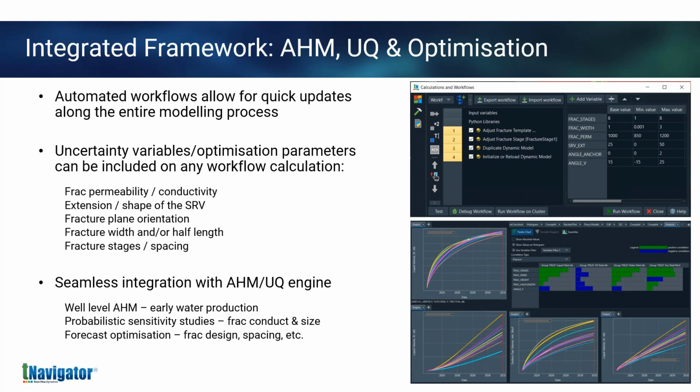Fracturing parameters among rock properties and pumping schedule can be set as variables to optimize the processes of fracking. The different modeling steps, either when using Fracture Simulator or when using any of the described hydraulic fracturing methods specified with direct inputs of the parameters, can be recorded into an automated workflow for quick updates of the modeling process. Uncertainty variables related to the fracture geometry, geomechanics parameters, PVT of the slurry, or the pumping parameters can also be added to the integrated workflow.